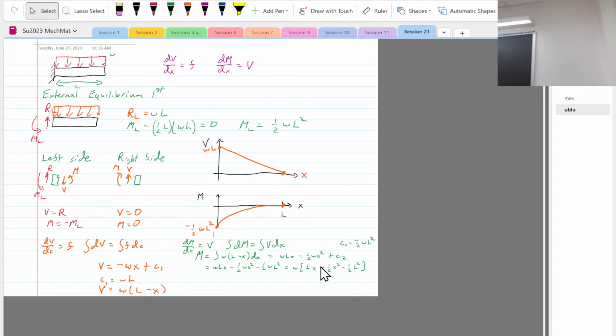There is a shear force, we agreed, right? If I move that over there, there's a shear force, TZ. Now, what's the equation for transverse shear? There's V over A, and there's VQ over IT. So if we're looking for transverse shear, it's VQ over IT.